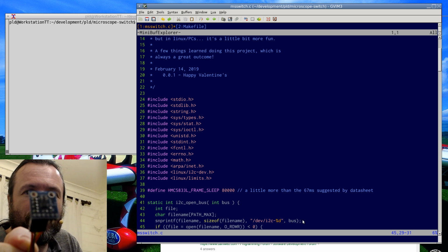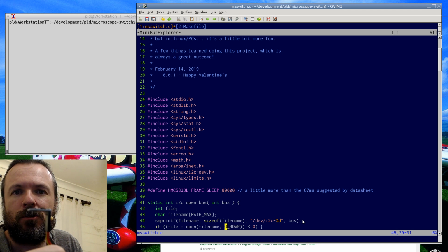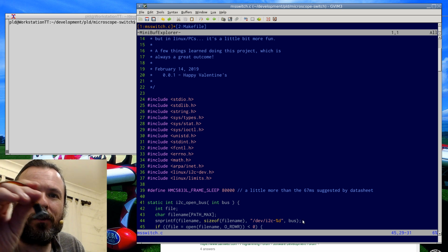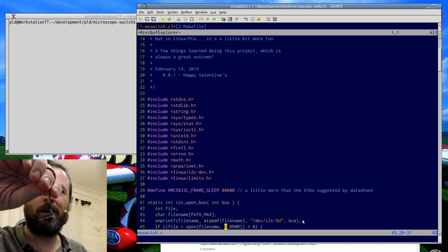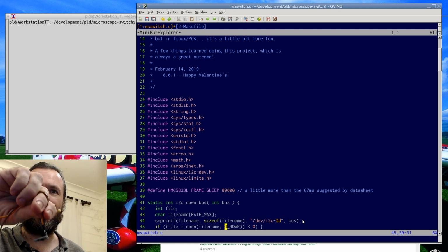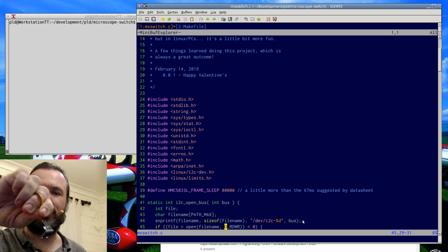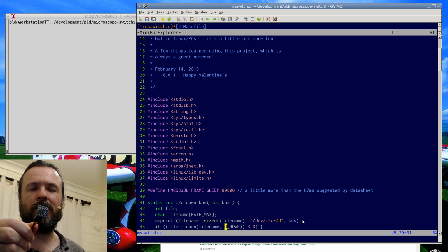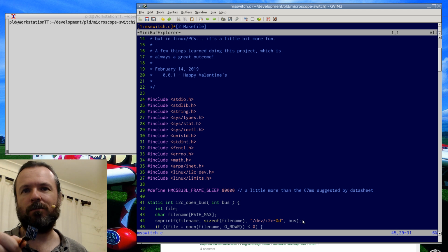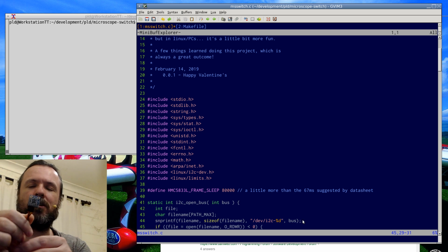So what this is, is a 3-axis magnetometer. Let's just call it a compass sensor. Even though it's 3-axis, we can still just use it for 2, so a planar type compass, which is what we want. The idea is, I put this on top of the microscope, and as you rotate the arm that holds the head out from its retained position into one where you're going to use it, the compass heading will change. There'll be a range of degrees where you consider the microscope to be in use. So that's the idea. This is an I2C device.